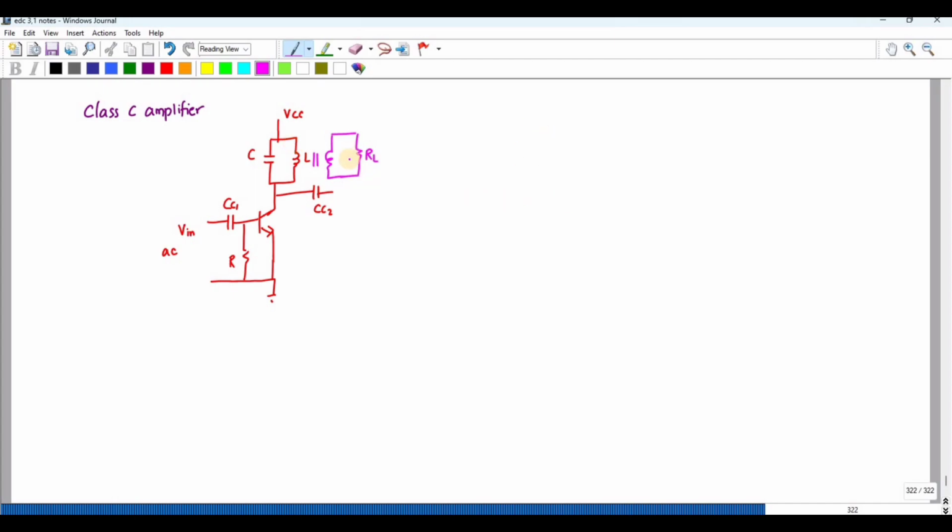And so this resistive load is replaced by a parallel tuned circuit. Why is it called a parallel tuned circuit? L and C are connected in parallel, and its impedance strongly depends on the frequency. So the use of the tuned circuit in conjunction with the transistor makes possible the selection and efficient amplification of a particular desired radio frequency.